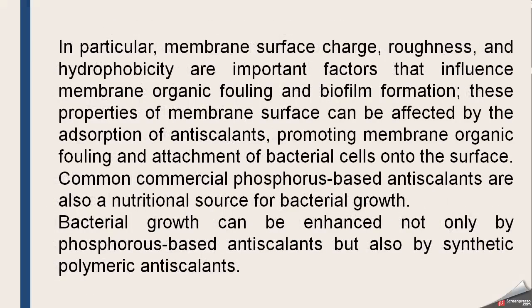Membrane surface charge, roughness and hydrophobicity are important factors that influence membrane organic fouling and biofilm formation. These properties of the membrane surface can be affected by the adsorption of antiscalant, promoting membrane organic fouling. And this basically provides the feed for bacteria cells, which can grow easily on the surface of the membrane.